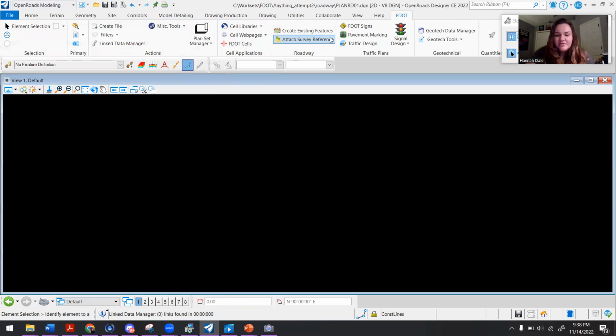All right, so now we're going to go over super basic stuff. So you know that the coordinate system is set properly because at the lower right corner of your screen, you should see a little world icon with a green check mark next to it. Now, if you're just doing random drawings for the sake of a CAD drawing for a simple report or anything, you don't need to worry about the coordinate system. But if you are doing an actual plan submittal for a specific project, it's really a key thing that you have this green check mark, because that basically means that whatever you're drawing is completely compatible with the actual map and world out there.